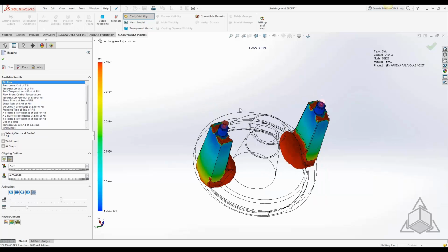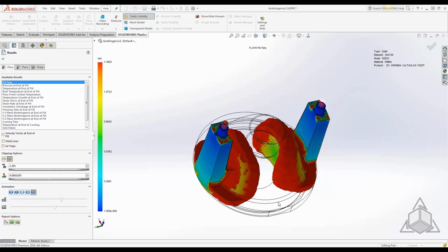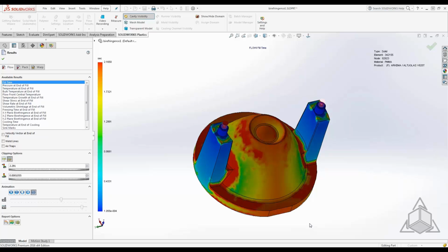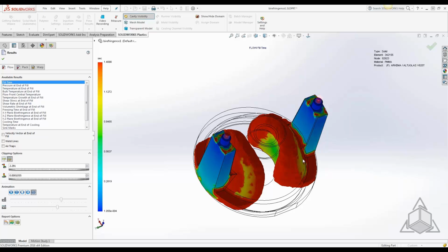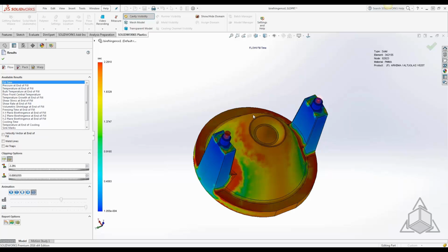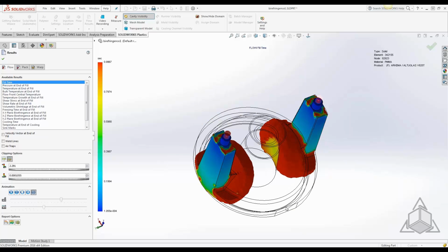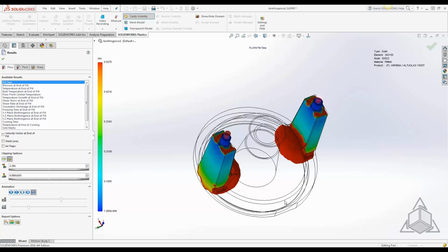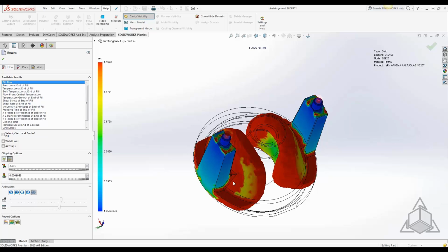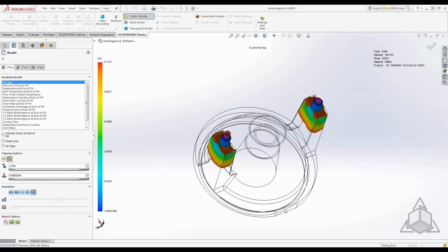So you probably see some knit lines down the middle here. What is interesting is that you can see how the polymer is forming together in the middle, and that will affect the birefringence results that we get as we look at it in a second.